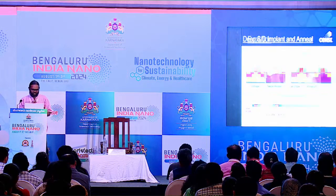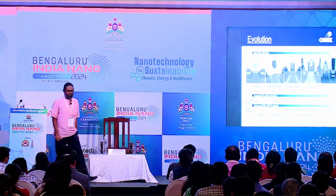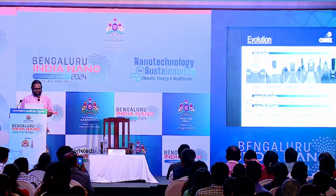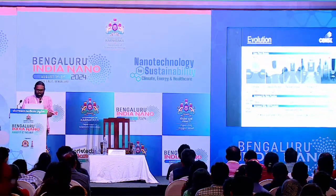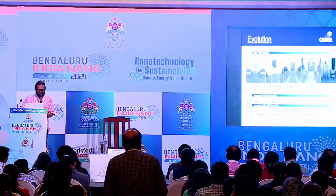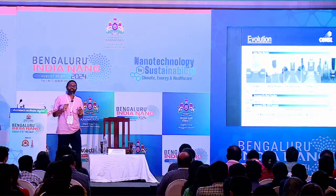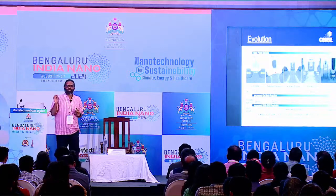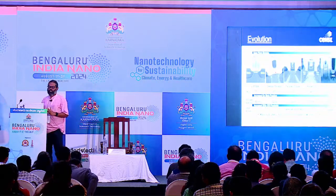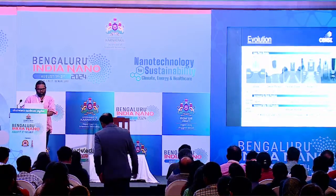And once those transistors are done, this is how they look in different generations, right? Going from the 90 nanometer node, which means 90 nanometers is the transistor size here, to 22 nanometer. They essentially look similar, but you can see some contrast there. These contrasts, this is a transmission electron microscope image. These contrasts are coming from the materials that people use. Though the architecture is similar, different companies will use different materials. That is their proprietary structure, so based on that, people use different structures.